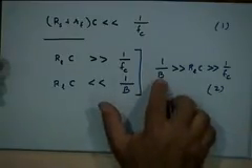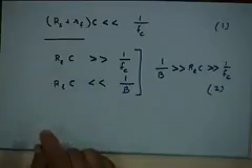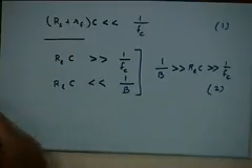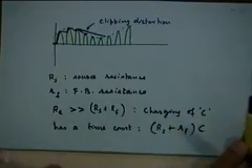You see here, why FC plus B? You are trying to track the envelope. FC doesn't come into the picture. Envelope has nothing to do with FC. The envelope is entirely a property of the message waveform m of t, right? The carrier frequency has nothing to do with it, right?